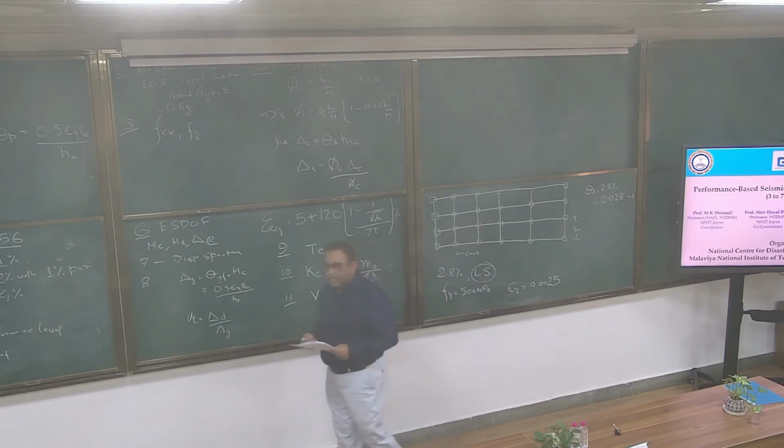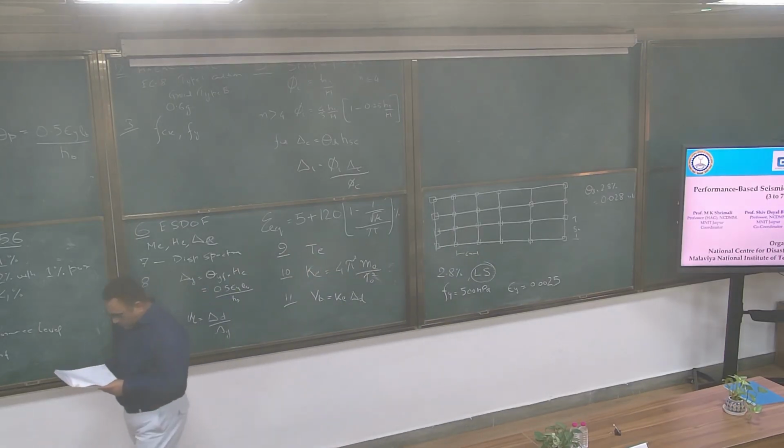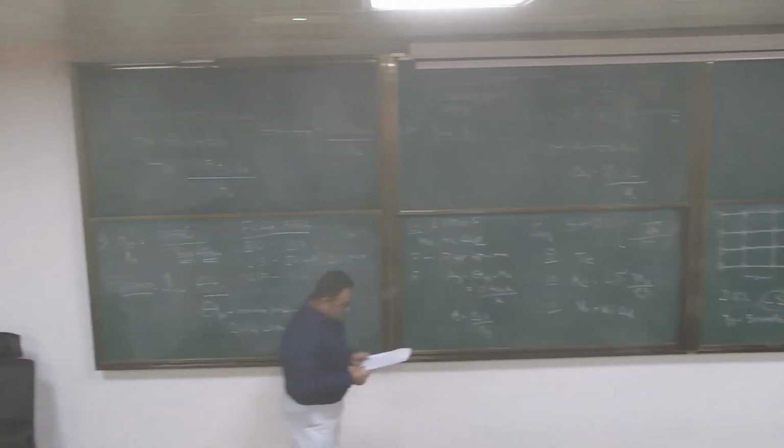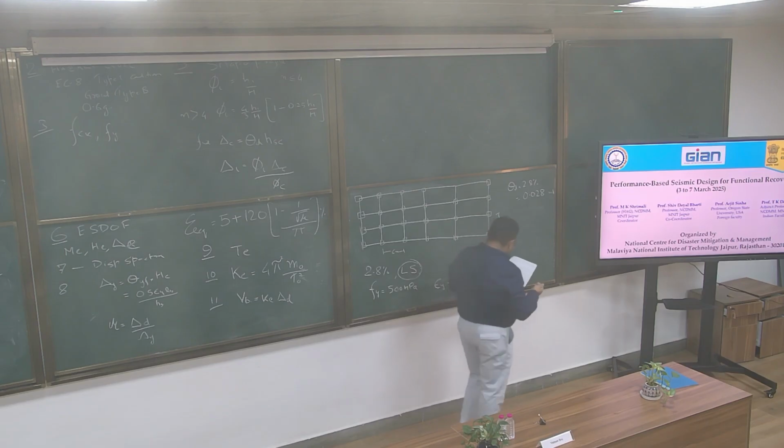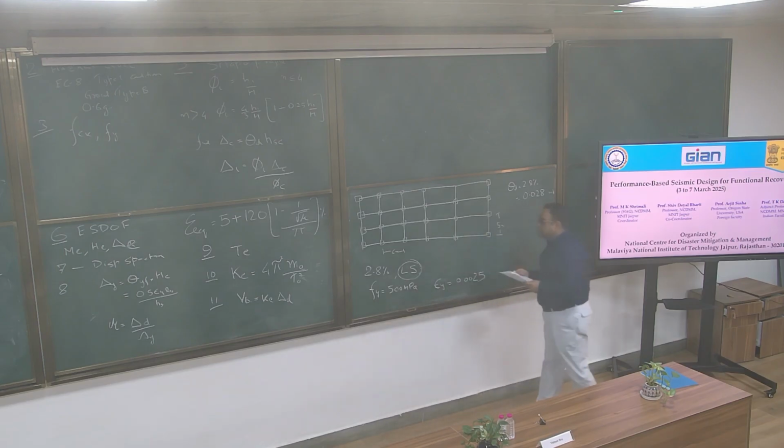And as per the FEMA guidelines, for life safety, we have some kind of transient drift requirement, and the corresponding guideline in ASCE 41 is that for life safety, our theta PB, or the average allowable plastic rotation, is 0.02. So the average allowable rotation is 0.02. Okay?